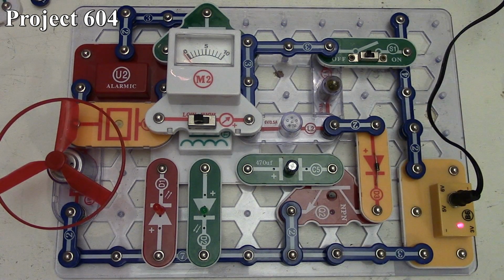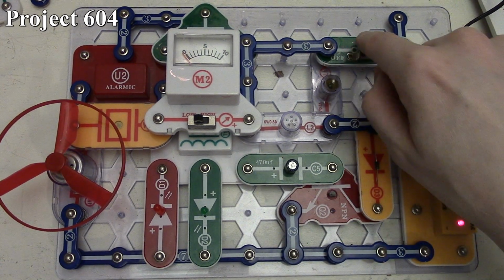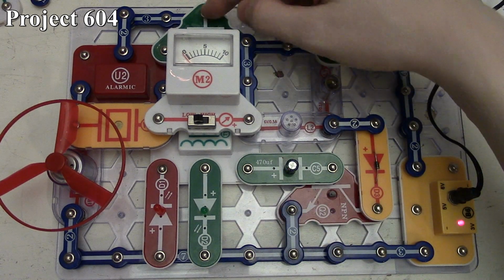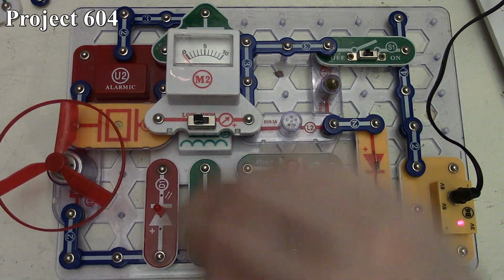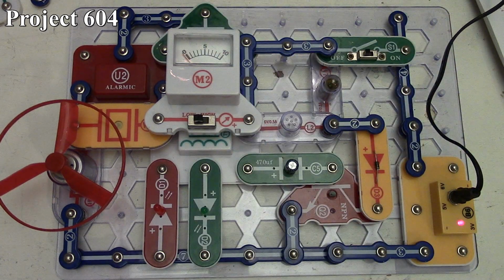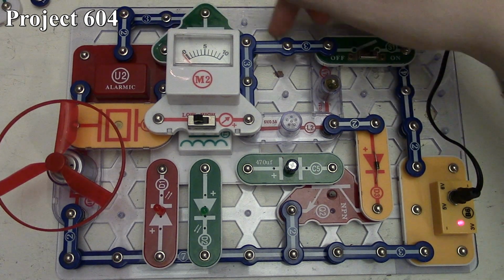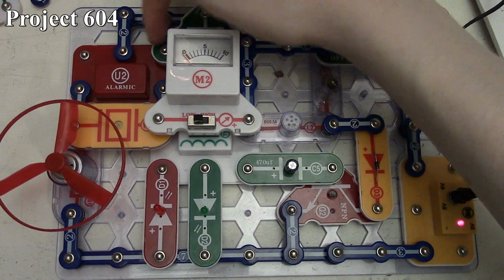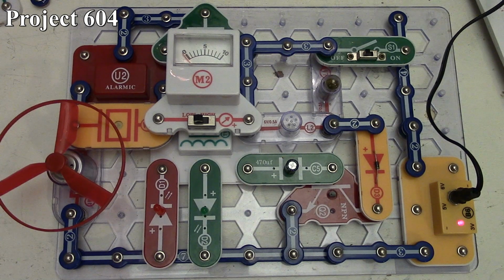So we have our 6-volt supply going to our slide switch to turn the whole circuit on and off. That then goes to a couple of things here. Number one, it goes to our PNP transistor, which is kind of situated under the meter here, and that is controlling the input on and off to our number 3 input of our alarm IC, while we have a constant supply to the number 2 input. So the PNP will be pulsing the number 3 input to our alarm IC on and off here.